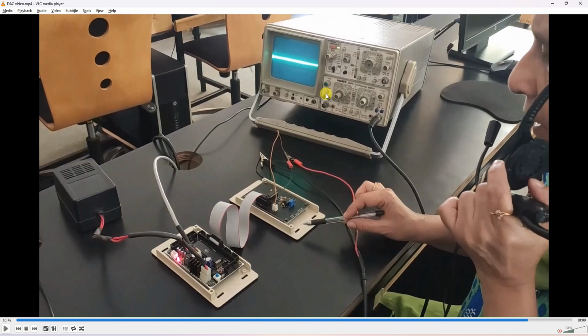And ground should be released. You press ground and adjust this. Turning this knob, you adjust to the horizontal level. Click on this button, then release the ground. After that, through this you can adjust this level. The vertical scale you can adjust to 2 or 5. Then you release the ground button.